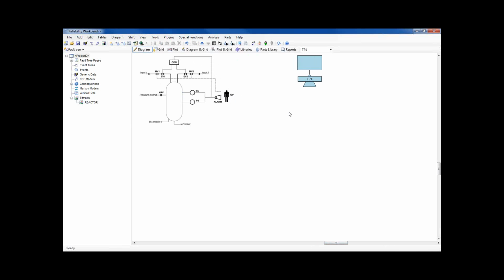Okay. Now, some guidelines on building the fault tree. When I described the safety shutdown system, I described it in the forwards perspective, starting with what happens and then what follows next. The reaction occurs, the sensors detect it, they send a signal, the valves shut. That's the way it's supposed to work. Fault trees are a deductive analysis, which implies a backwards thinking.